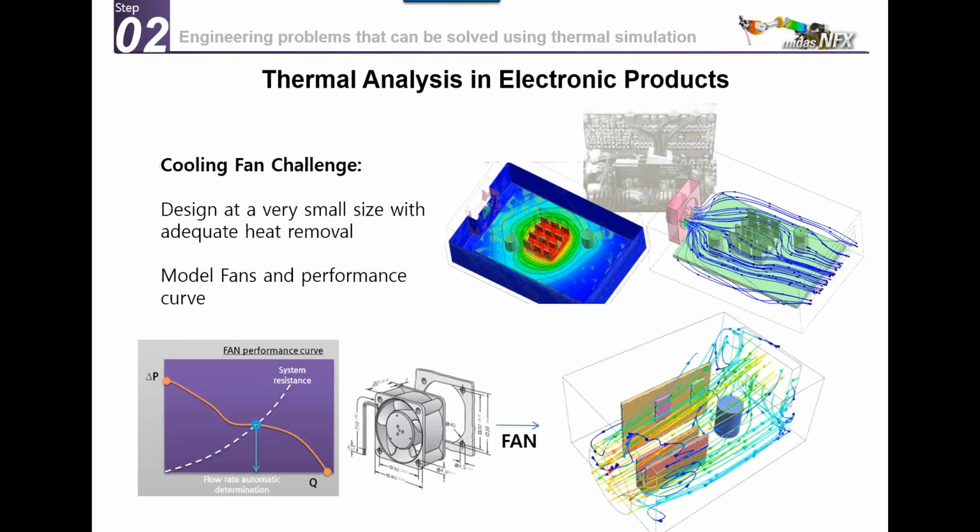So you have also a lot of challenge for the cooling of electronic devices. Because all the PC boards become smaller and smaller, and you need to have powerful fans to remove the heat. At the same time, simulation allows you to simulate all that directly on your computer. You can just use a fan model and define your fan curve, and it will then tell you how much time it will take to cool the system.